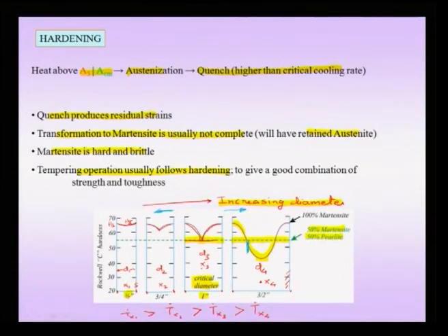sizes. So, you have here in this range of the diameters a sample in which you have a central core. Say for instance, suppose I am talking about a cylinder which is long in this section, that means I have a central core which I am shading here, and this central core does not have even 50% martensite and therefore, is soft as compared to the surface, which of course, has felt the full severity of the quenching medium and therefore, is 100% martensite.